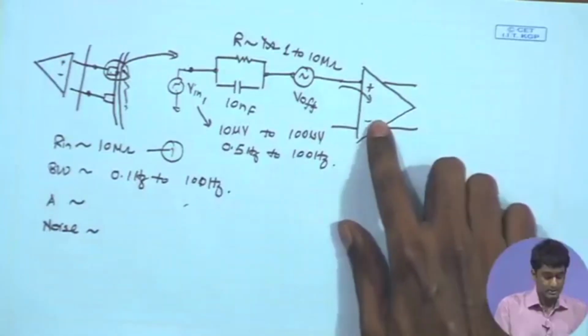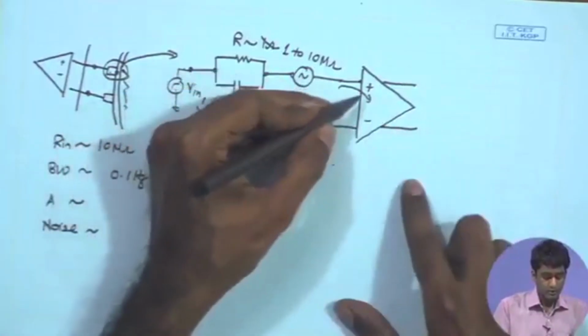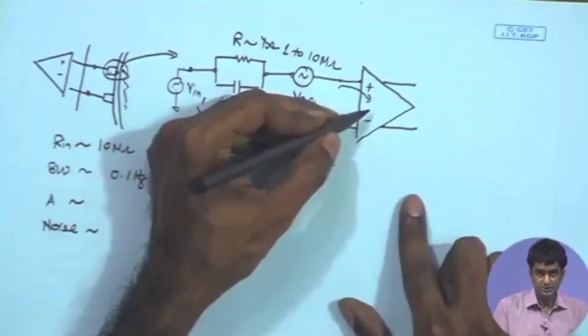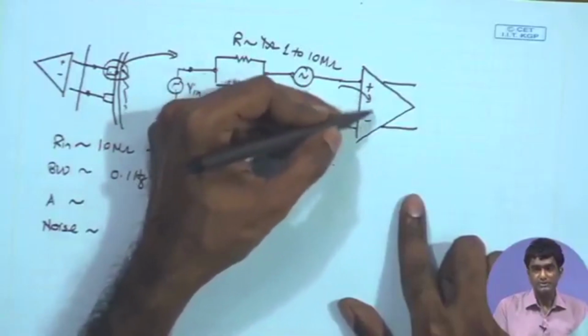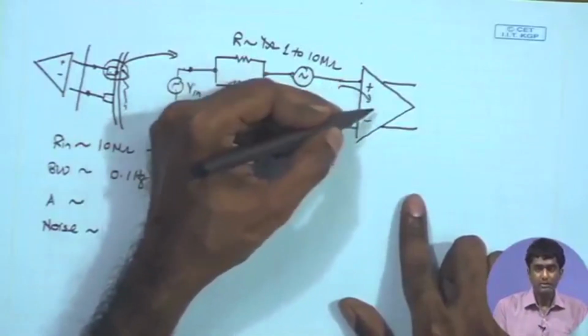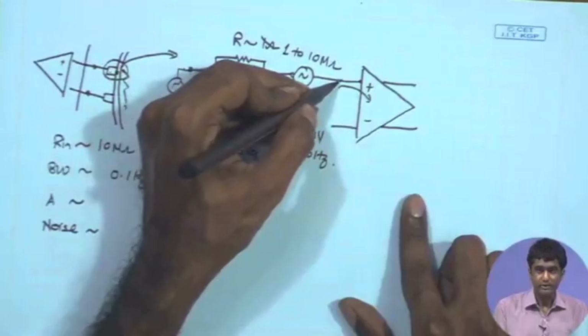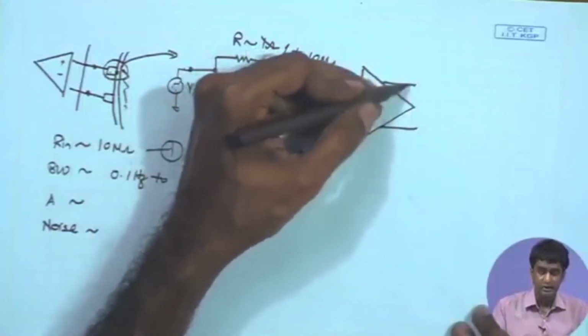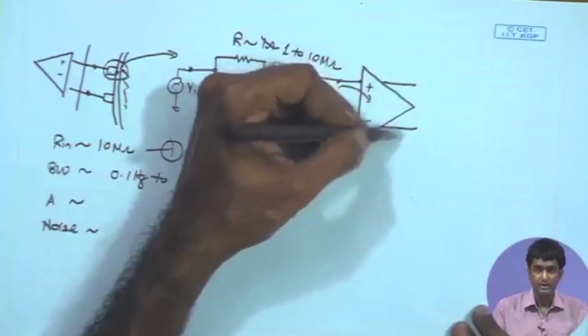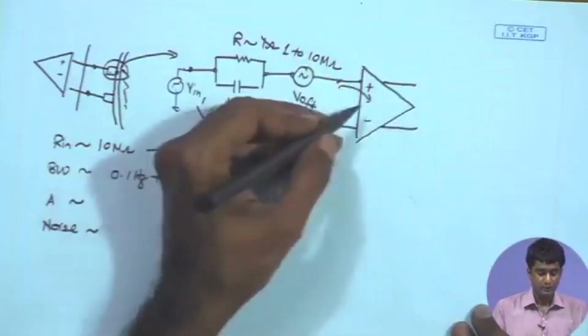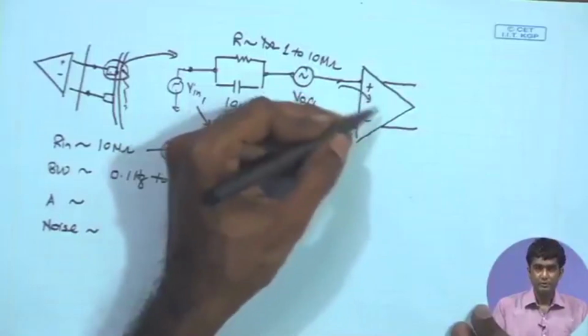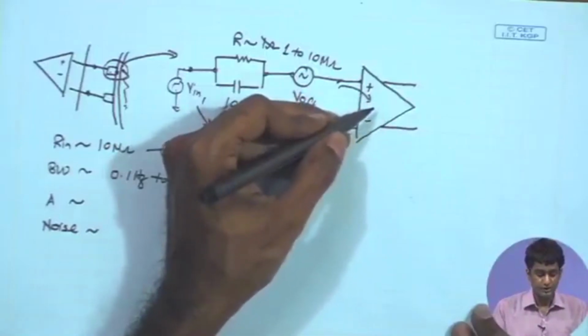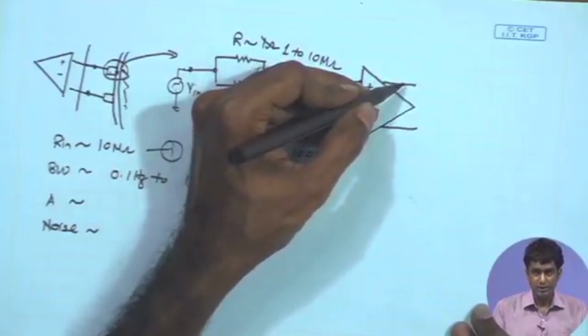So, during the basic noise analysis, we have seen that the total noise contribution of the transistors in a particular circuit can be modeled as an equivalent input referred noise. Ultimately, the signal of the circuit will be available at the output. So, we will be looking at the signal available at the output of the amplifier, and therefore, if the transistors in this amplifier are producing noise currents, noise voltages, their effect will be definitely visible at the output.